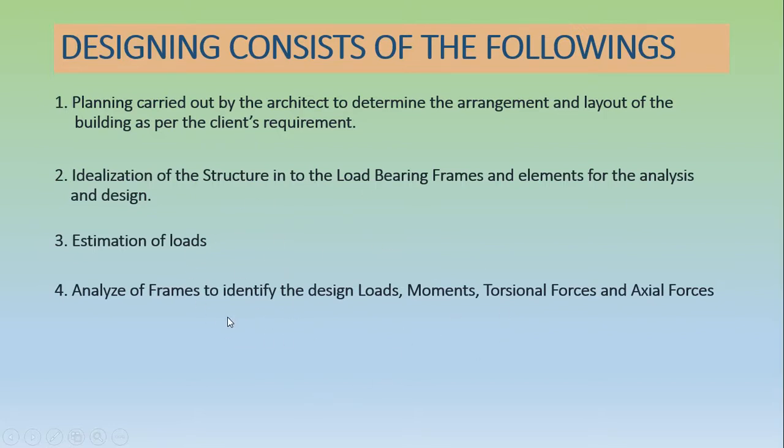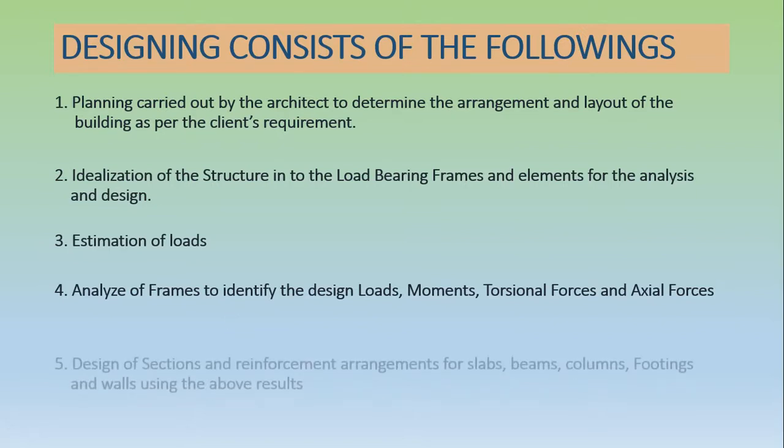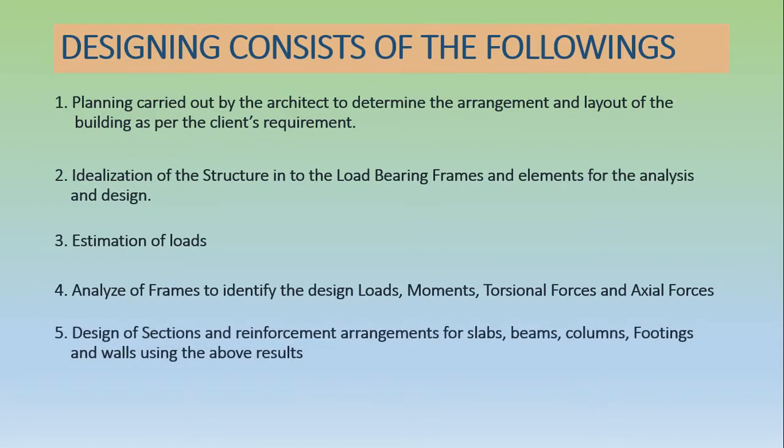From the bending moment envelopes you can get the maximum bending moment and shear forces for the design works. Then according to those envelopes, you can design the sections in accordance with the instructions given in BS 8110 Part 1, 1985.